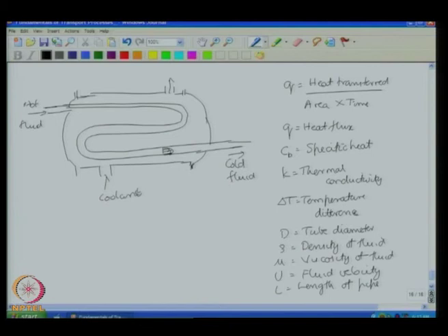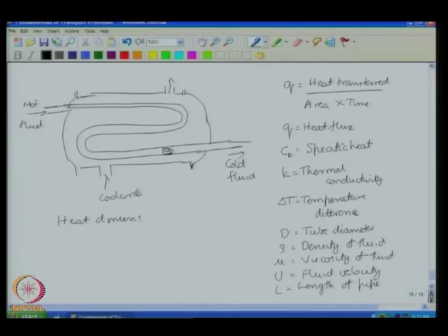So, here the assumption is that the heat flux is an energy per unit area per unit time. However, if there is no conversion of heat energy into mechanical energy, then the heat energy can be considered as a dimension all by itself. There is no conversion between heat and mechanical energy, so the heat energy has to be conserved. So, rather than consider heat and mechanical energy as equivalent things, we can consider them as different things, and assign a different dimension, heat, with the symbol H.